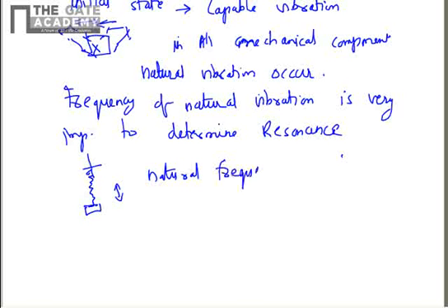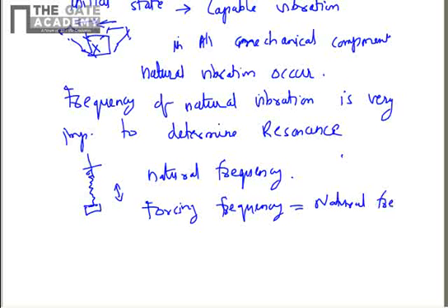So if in a system you are forcing at natural frequency, that means you are supplying the energy at natural frequency, then the amplitude of oscillation will grow, and sometimes the amplitude of oscillation can go up to infinity also.